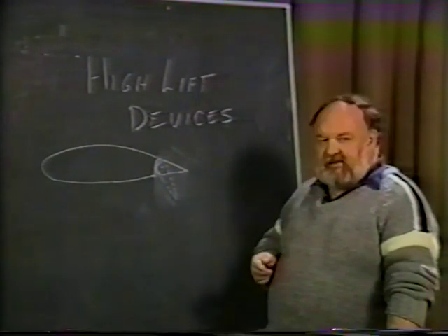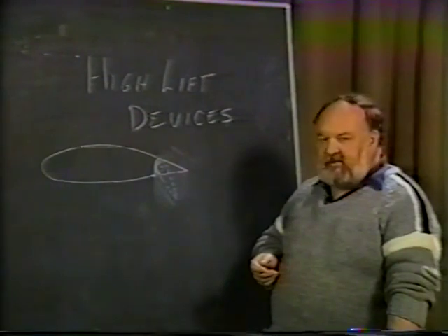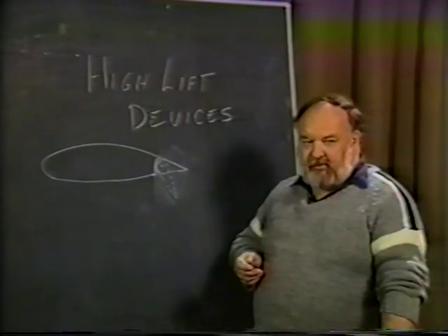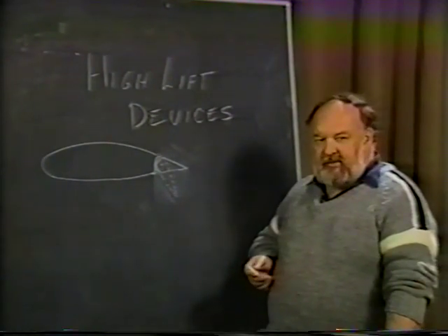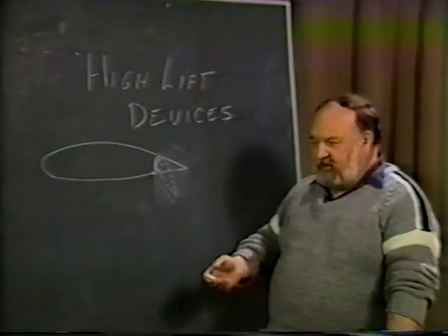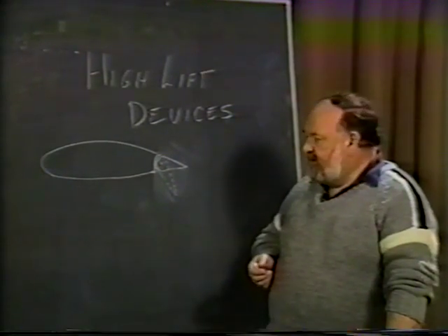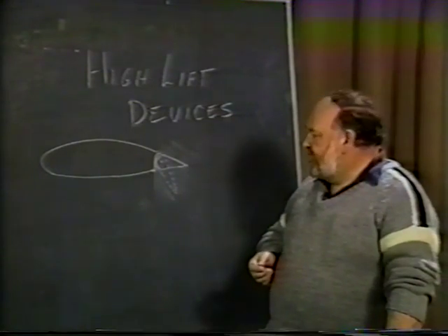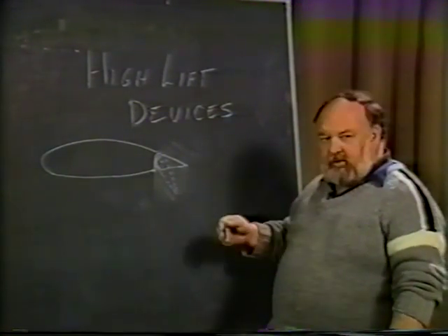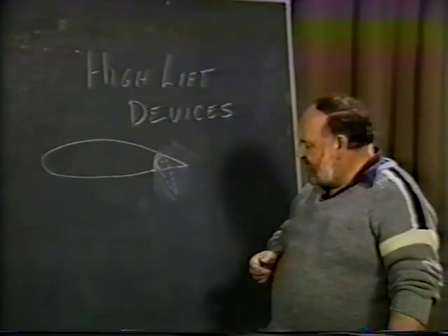And it's relatively simple to manufacture. You have a hinge point inside the wing itself, so you do not have any external brackets or anything like this. The hinge moment load, so therefore the load of activating it, whether it's electrical, hydraulic, or just manual, is a little bit higher than a split flap, but not too bad. Obviously, the length of the chord of any of these flaps controls the amount of lift. We can go into that in a little more detail later.